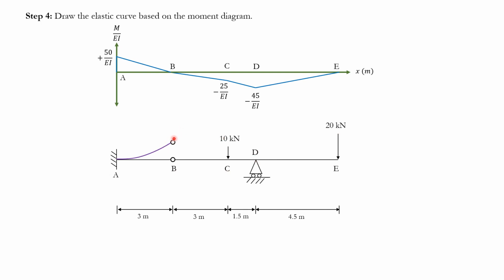And then here, since this ruler is separate from this one, right? It's a separate body by itself. It's not going to continue. This fixed support doesn't let this go up, okay? Because of the compatibility of deformations here, as you know, the fixed support just has to be zero slope and zero deflection. This has to go like that. If it wasn't like that, then it would be different. If it was a pin, it would be a different situation. But since it's a fixed support, that's just what's going to happen.